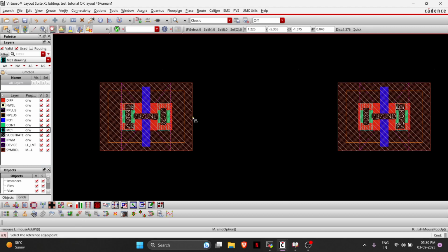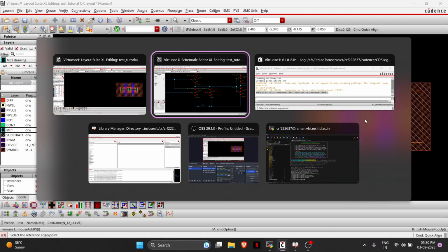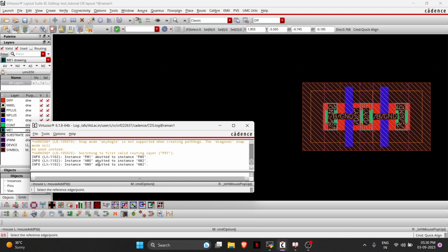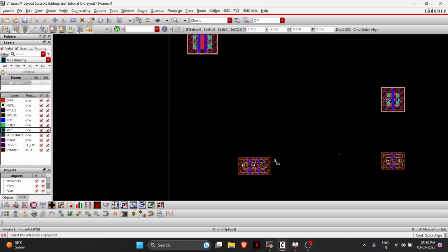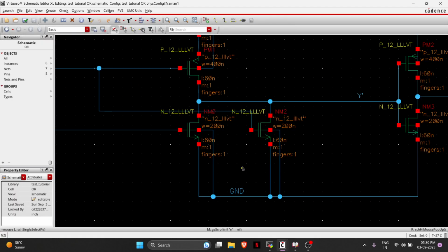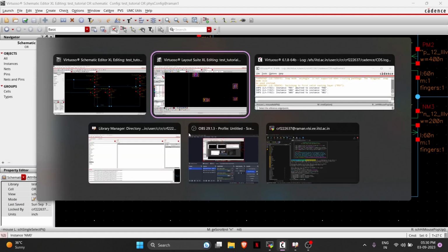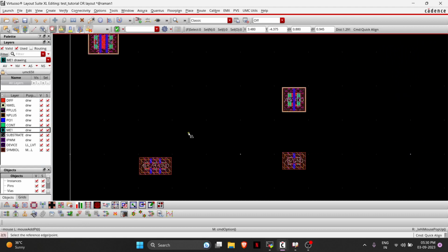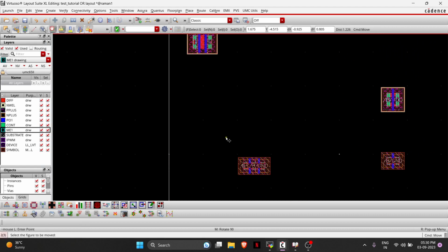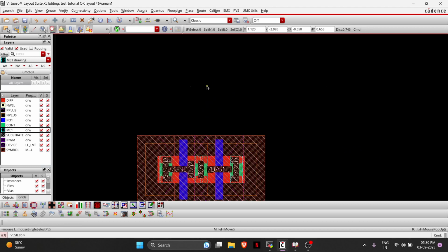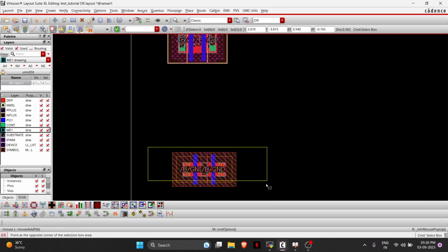You select this. Now I can align them. If I align them, now drain and drain are abutted. I can check from here. And then 0 and 2 are abutted. You can check and see the method. And 0 says and then 2. Yeah, now it is time to move, select both of these. And if you select one of these, the button will go away. So select both of them.